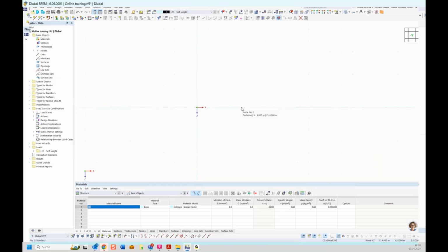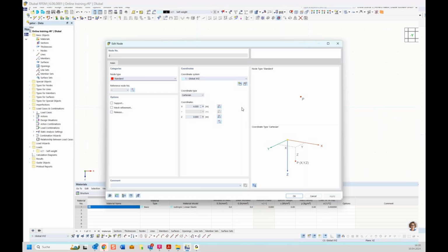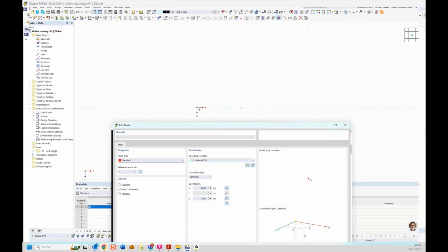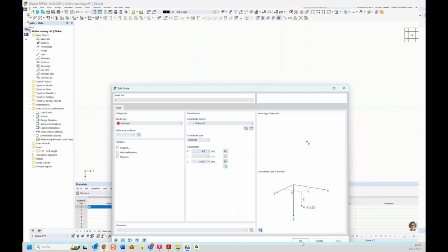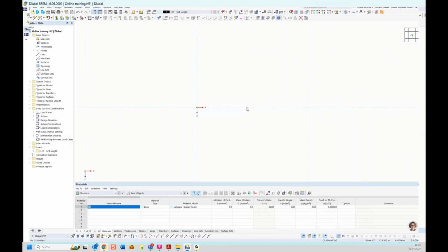First, I can click on this node, and in this case it fits perfectly because we start at the 0, 0 coordinate. Then I could change the X coordinate to 450 and say OK. And now you see it's at 450, how we want it. But you also have another option. You can go to this button, settings on work plane.